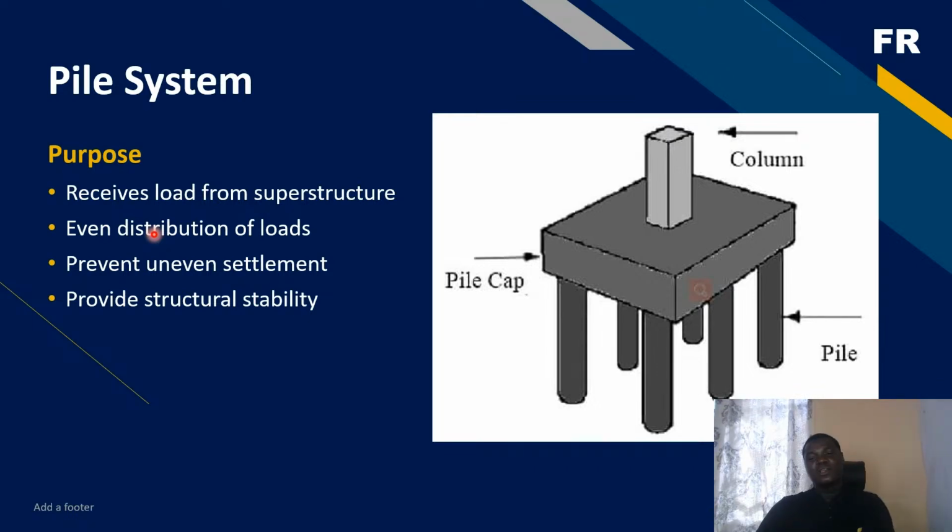So nowadays you see some people practice piling in such a way that they neglect the pile cap. If this is not properly done, like in the case of a raft plus pile foundation, the raft slab is going to serve as a pile cap. But if you are not doing it that way, then what you are doing is not right.